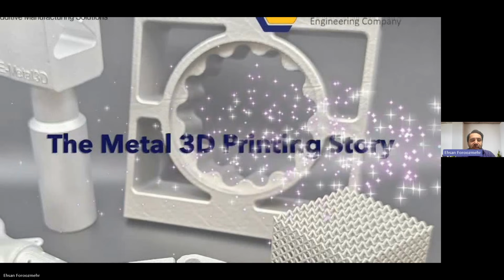The next step in this process is slicing. Virtually, with a very thin layer thickness of around 60 microns or less, we slice the part and transform the complexity of the geometry into thin two-dimensional features that are much easier to manufacture than a three-dimensional part. As you can see in this section of the video, while the scroll is going up and down, you see through the part and its different layers. That shows where the supports are sitting and how they are acting, and this is the information that is going to transfer into the machine.